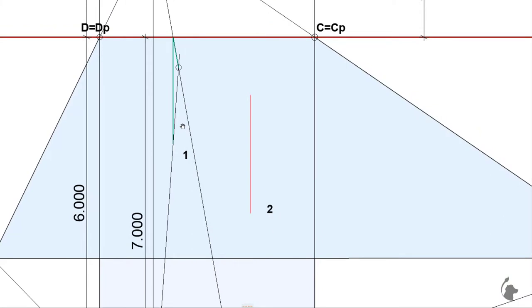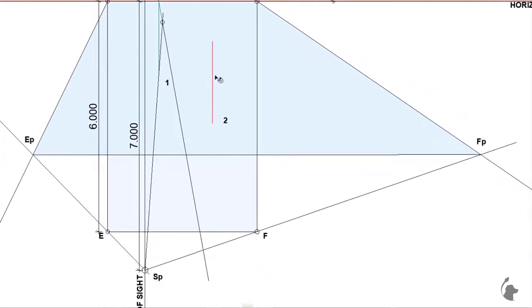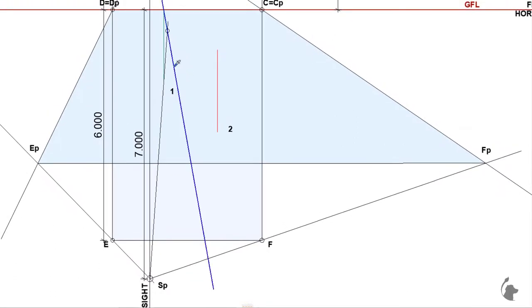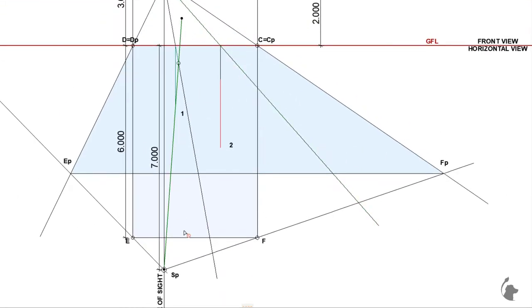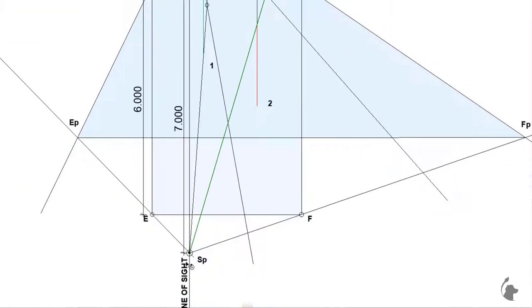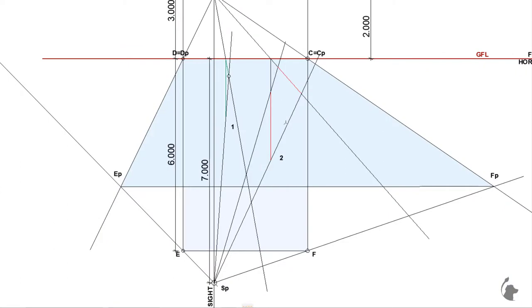But what about the second line? It's not connected to the ground floor line, so we can't just bring it into perspective yet. We need an auxiliary construction line, so we'll gently extend it to the ground floor line, and from that point we'll bring our second line in perspective. Now, to measure its distance, it's very easy. We just need to draw 2 lines from SP through the first and second point, delimiting the segment, and we have it in perspective. Step 8.